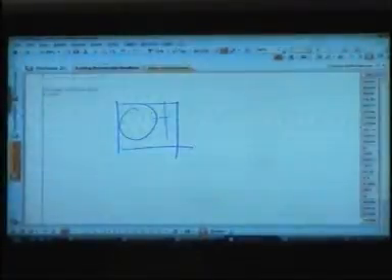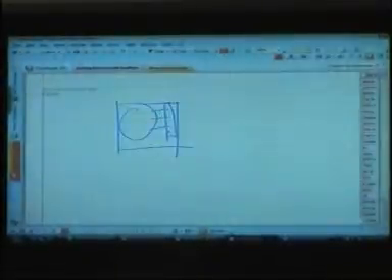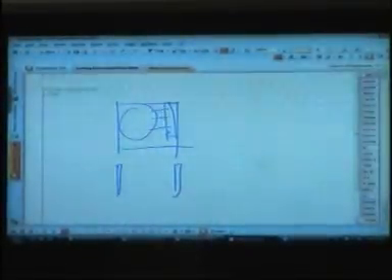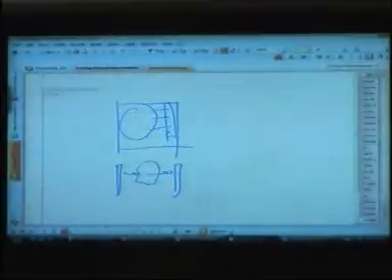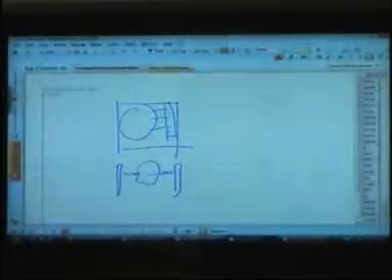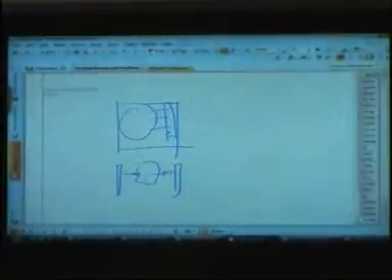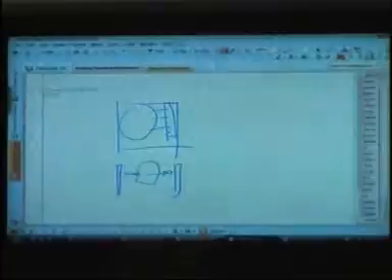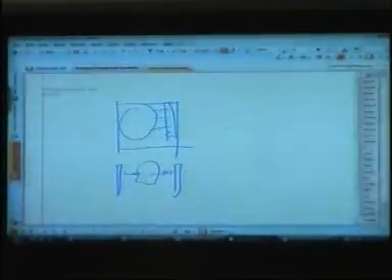So usually the person who is actually partitioning the design must make sure that each design has all its outputs registered. And the reason is, the timing is always register to register. Once we say timing, then somebody comes and claims that my design is working at 40 megahertz, and you want to make sure, this is the target clock which you give to 10 engineers, that the design must work at 40 megahertz, because this is my target speed in mind for this chip. So even if there is a single path out of a million paths which is not working at 40 megahertz, you are in trouble. Right? So you say every engineer's design must work at 40 megahertz.